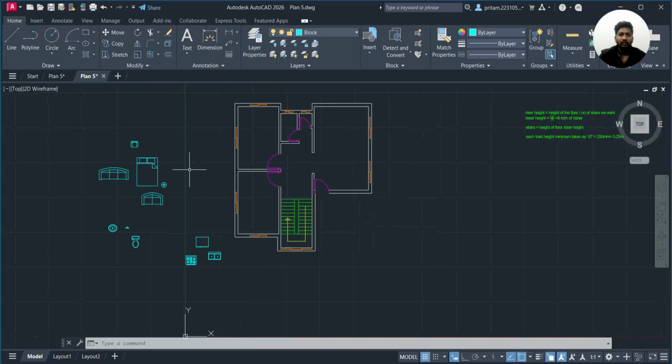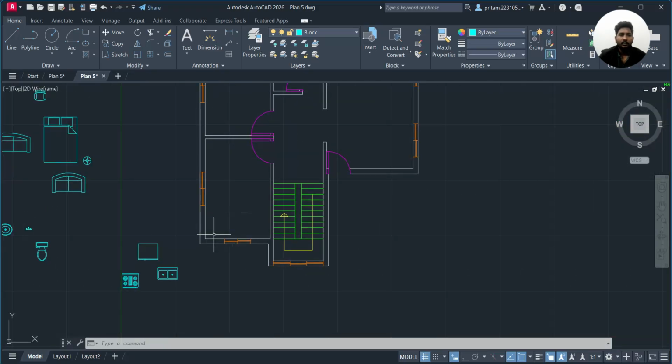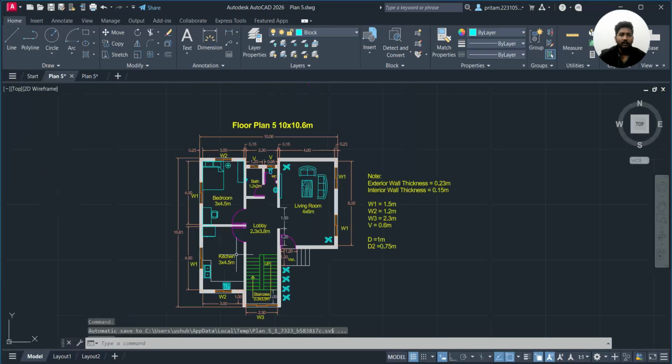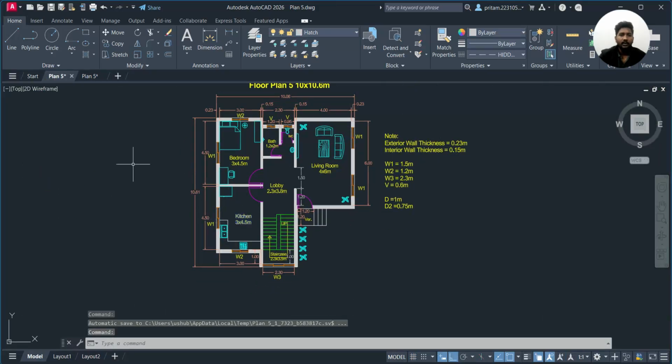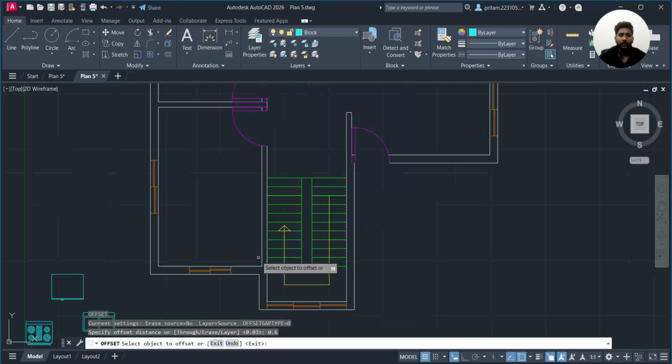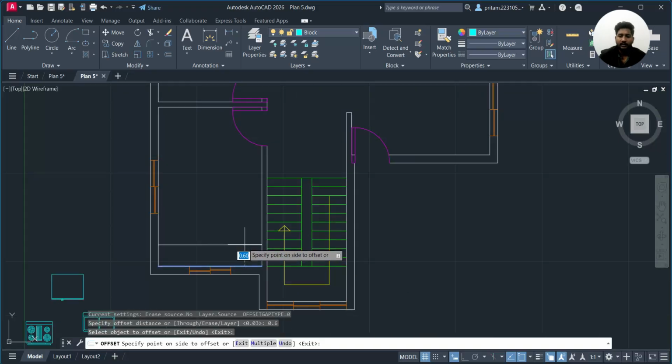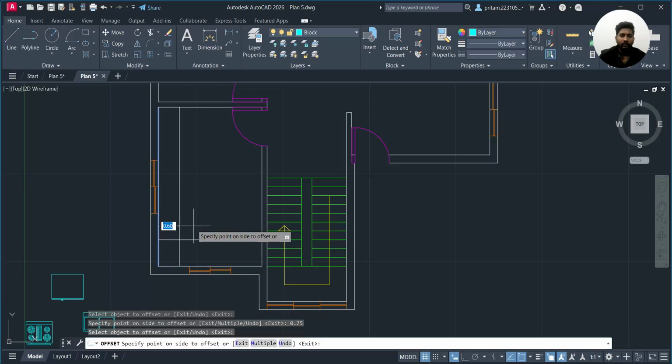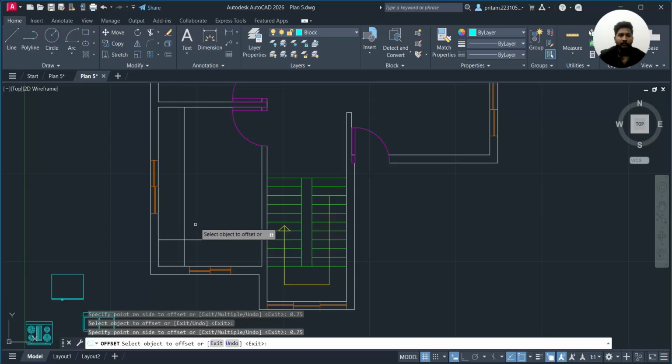So how do we add this now to our model? You can see that this is the kitchen part, right? For this kitchen part, the OTA and all these details should be made. So go to our plan. In it we just type offset. We offset it by 2.5 feet. We take 0.6 meter for the 2 feet format, and just drag it above, or let's take 0.75 as the offset for the OTA. That is 0.75 means 2.5 feet.